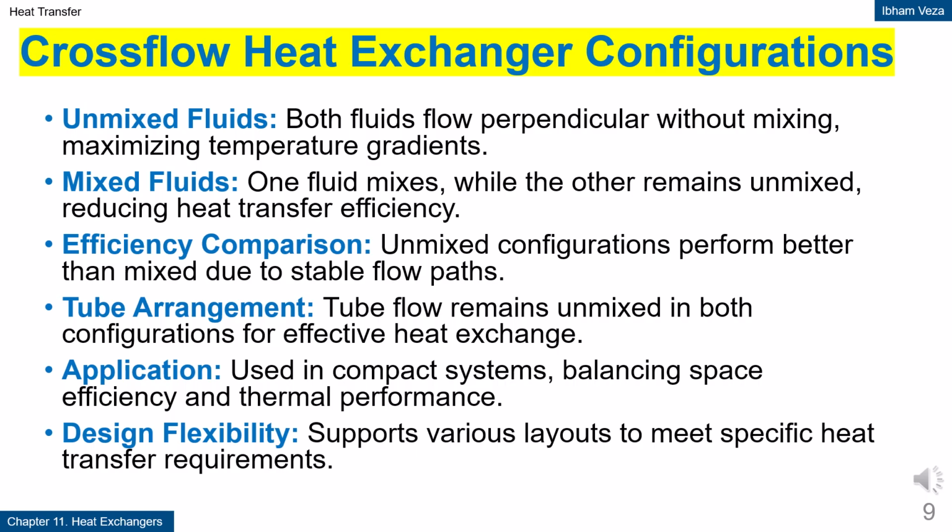Crossflow heat exchanger configurations. In crossflow configurations, one or both fluids can be mixed or unmixed. Unmixed conditions generally provide better thermal performance. This is because the temperature gradient can be maintained more stably. Tube arrangement and flow paths strongly influence this behavior. This configuration is often chosen for systems requiring compact design.